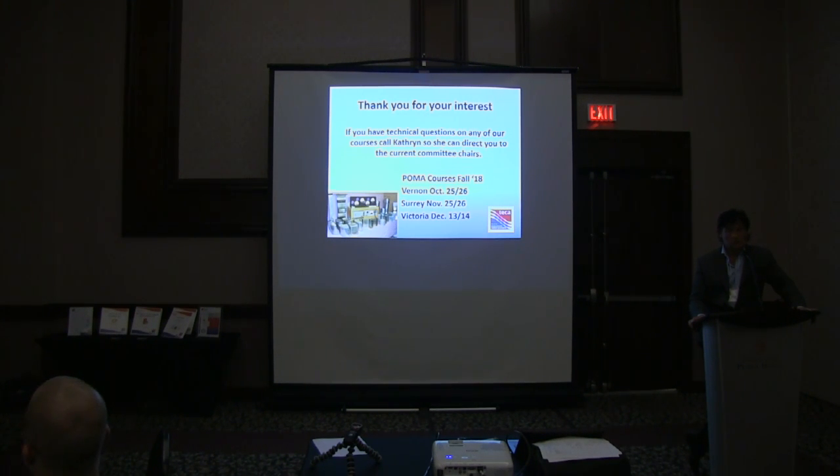Yeah, generally speaking, if it's not labeled, it's probably 6 or below. If they get 8, they get brownie points from, I forget the commercial program. They get brownie points for that. So if it isn't labeled, you'll find it will be below 8. So if you see a 1 inch filter, wouldn't you encourage people to go for a lower MERV rating because of the static pressure across them?